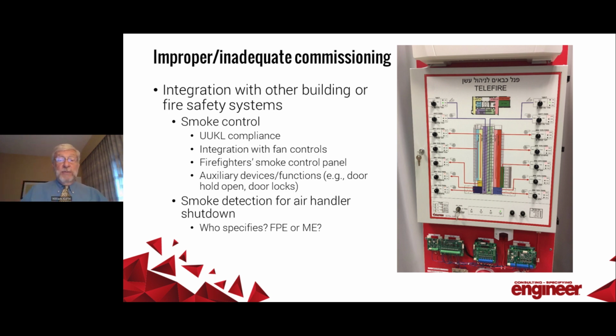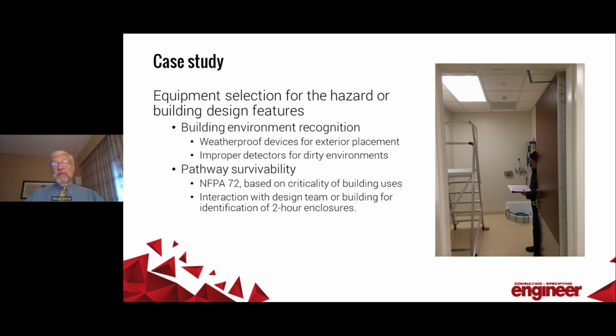We had 25 people die in a hospital fire in Saudi Arabia. One of the factors was that the air handling system, which happened to be a plenum system, did not shut down by detection of smoke. They talked about different types of detectors and the need to identify detectors that are appropriate for the fire, but also appropriate for the environment.